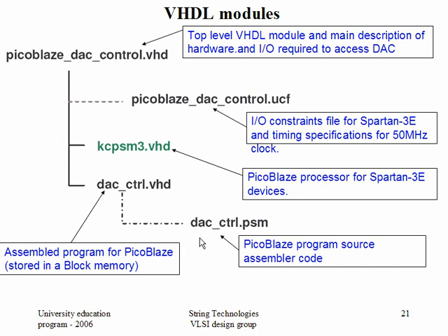Okay, now you see how this is going to work. I have basically one assembly program. This is a PicoBlaze program, assembly code. This assembly code I compile, something similar to a cross compiler, and I generate the VHDL module. What is the VHDL module? This is just like a ROM, read-only memory, which has the machine code of my program. Isn't that how your microprocessor works?